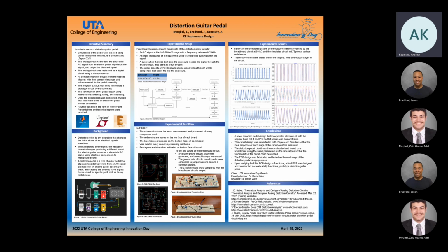As you can see, the signal is going to be sawtooth in every case. However, the frequency domain of that signal is altered as the tone or clipping potentiometer is varied. So you're going to get a slightly different sounding signal as you vary the distortion potentiometer.